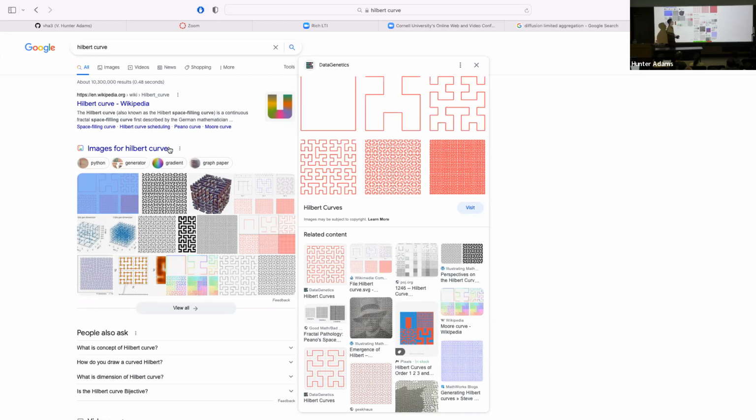You associate the color or the intensity of that pixel with a frequency. And then you take this Hilbert curve and you stretch it out into a line, and you use direct digital synthesis synthesizers to generate the frequencies associated with each of the pixels that you saw so that you get a unique sound associated with a picture.